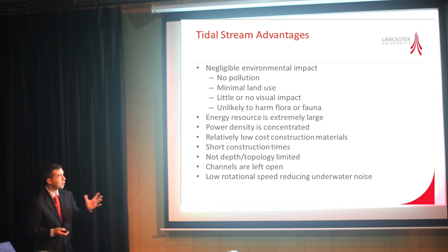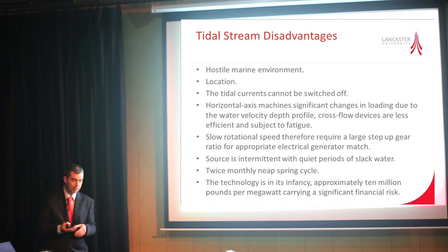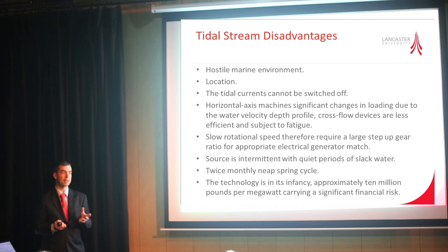To give a balanced talk, however, I should perhaps mention some of the disadvantages. It's not a win-win-win. We still have to be aware that although the tide is predictable, it is still intermittent. We get periods of high tide and low tide, and at those periods we have slack water when the tide isn't moving, and when the tide isn't moving, we're not able to generate power. Fortunately, the time where the tide comes in and out around the UK coastline is at different times, and therefore by having a series spread around the coastline, we are able to a certain extent to neglect the intermittency by having power generated at different points.